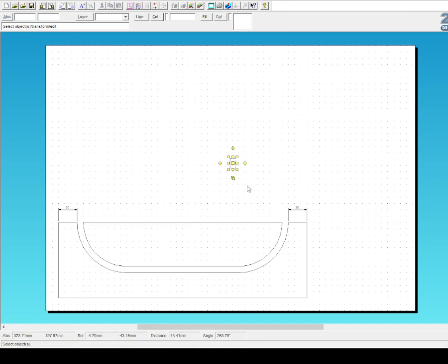I'm going to copy this shape, flip it, and mirror it, and use the move or copy selected objects, replace, and I've got my attach still switched on. I attach the top of this line to the end bit of that line, and I have a square.